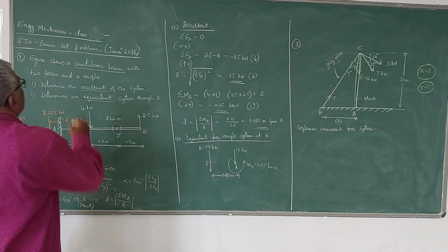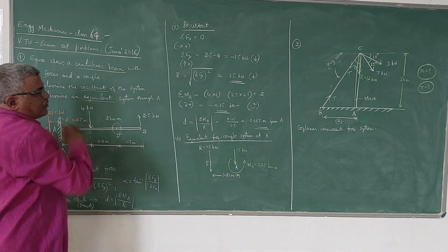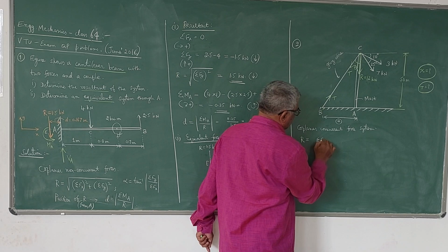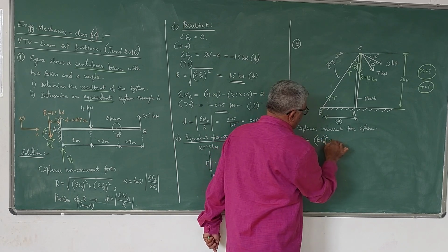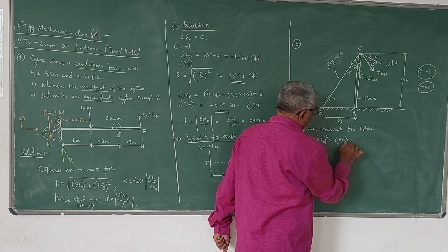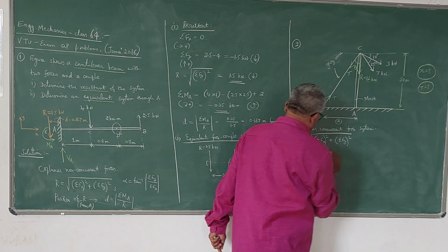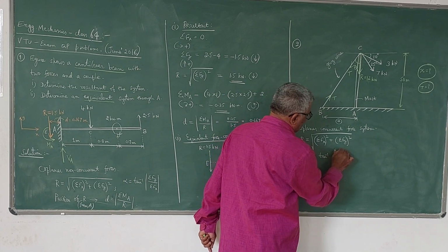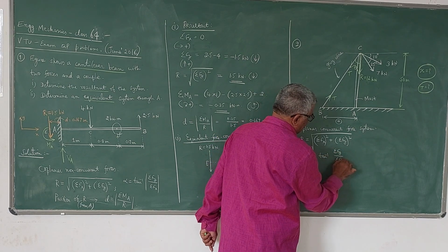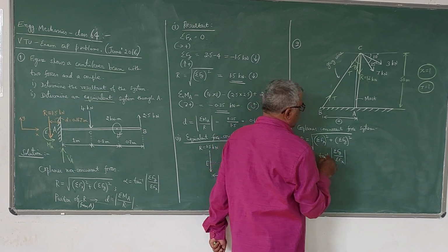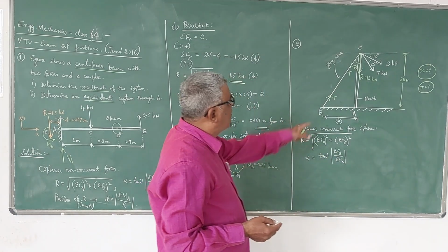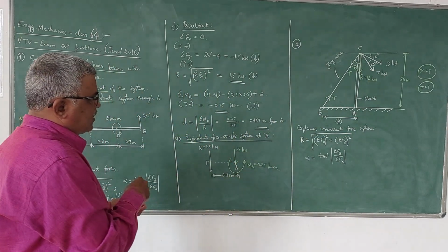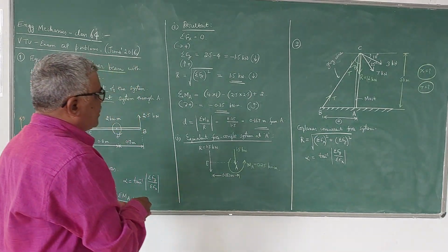So here, in this case, you have the equation for the resultant: magnitude is given by the square root of sigma Fx squared plus sigma Fy squared. And of course, the angle made by the resultant with the horizontal, alpha, is tan inverse of sigma Fy by sigma Fx. Of course, here there is no need to find the position because the resultant also passes through the point of concurrence C here. So now let us use the same concept we did in the last problem.